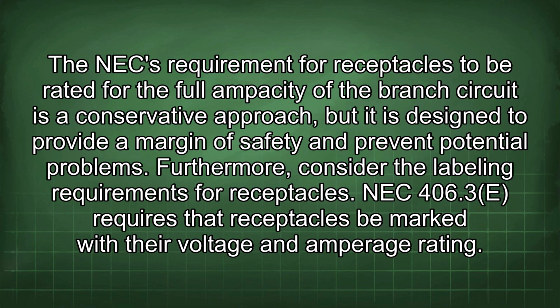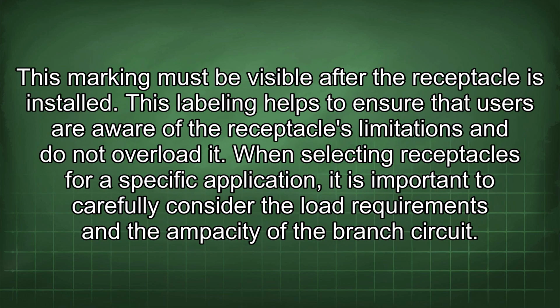Furthermore, consider the labeling requirements for receptacles. NEC 406.3E requires that receptacles be marked with their voltage and amperage rating. This marking must be visible after the receptacle is installed. This labeling helps to ensure that users are aware of the receptacle's limitations and do not overload it.